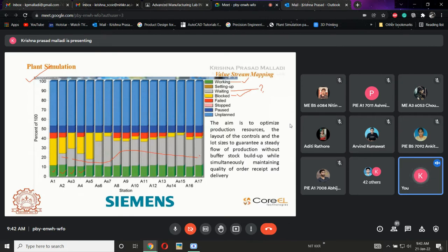I will explain. There are one, two, three, four machines. Four machines are connected in a line. This is called a product layout. In this product layout, a product is entering here. Each output needs to be the next input, and finally you collect the output. Now all the machines' processing time is the working time. Say all the machines' processing time is 2 minutes.